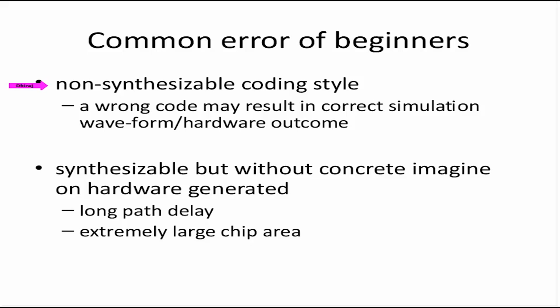For example, $display, $time, hard-coded delay values in Verilog are all non-synthesizable. They are not even recognized by design compiler. The Verilog compiler inside design compiler is quite different from the Verilog compiler of a simulator. So we have to keep that in mind while coding.